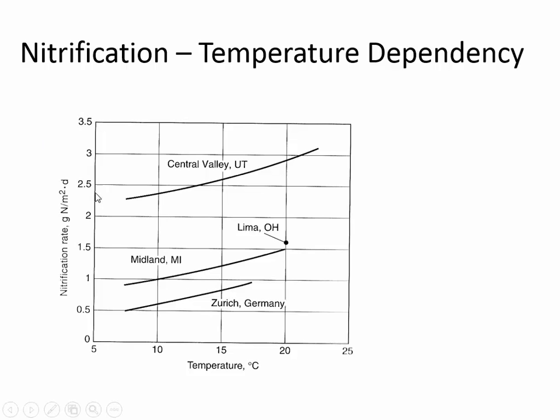And there's a big poultry operation in Central Valley, Utah, where trickling filters are used for agricultural wastewater, and they have pretty effective removal of nitrates, and you can see that in other locations they've had 5 times lower the rate of removal, but the trend is always the same, that when you have higher temperatures there's higher rate of removal for nitrates than at low temperatures.